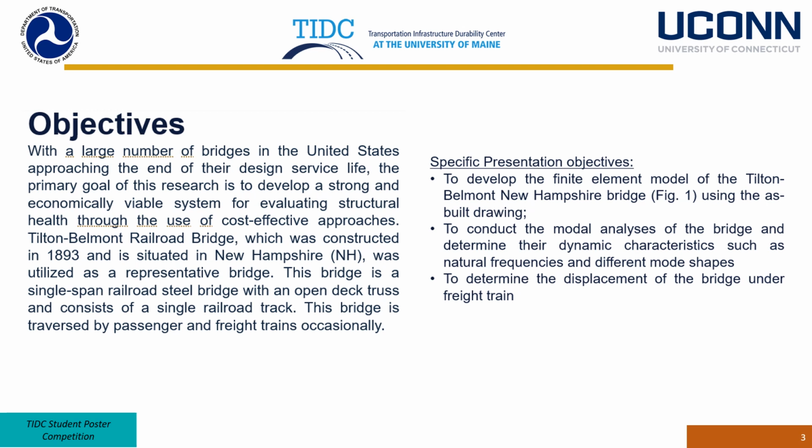So going into specific presentation objectives, the first one is to develop the finite element model of the Tilton-Belmont New Hampshire bridge using the as-built drawing which has been provided by New Hampshire DOT. The second objective is to conduct the modal analysis of the bridge and determine its dynamic characteristics such as natural frequencies and mode shapes. And the final objective is to determine the displacement of the bridge, static in this case, under the freight train.